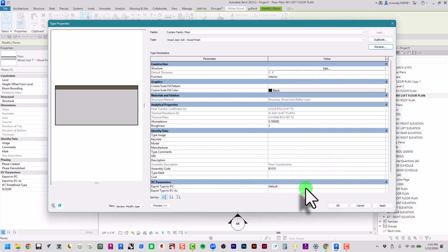Now, how do we know what type of framing we need? Right, we know that our walls are 2x4s. Nowadays, they actually want you to have 2x6 walls. But for a tiny house, that's going to eat up a lot of space, so we'll just keep it at 2x4. 2x6 walls allow us to host more things, such as plumbing and insulation. Right, so to make better use and be more sustainable, we can have a shell that's thicker and therefore can resist a lot of thermal properties of the exterior and keep the home conditioned without mechanical conditioning.